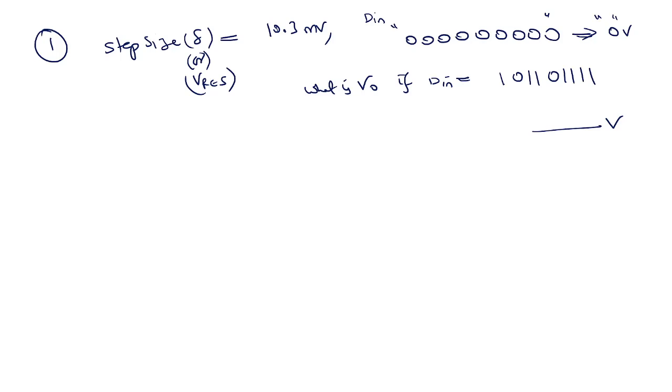Step size, remember guys, step size is also called resolution. Resolution is 10.3 millivolt, and for D in 9 zeros, output is 0 volt.